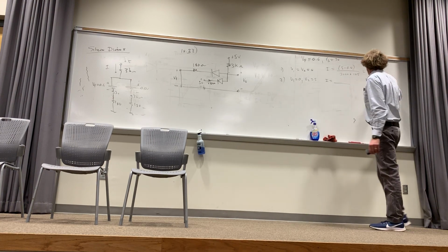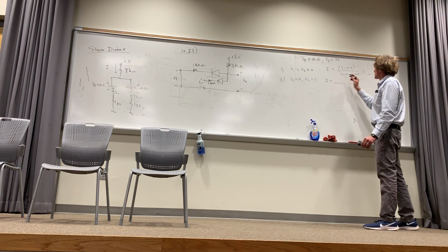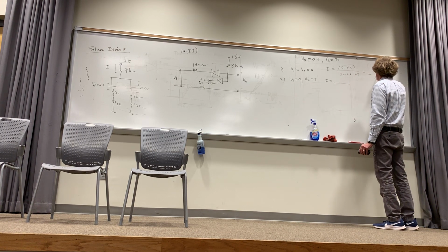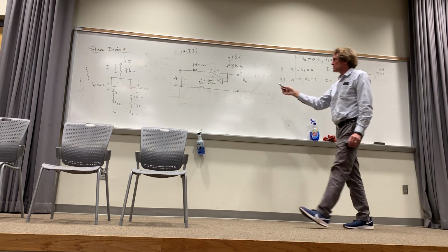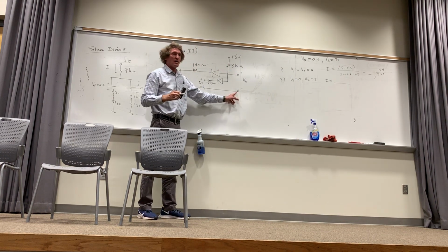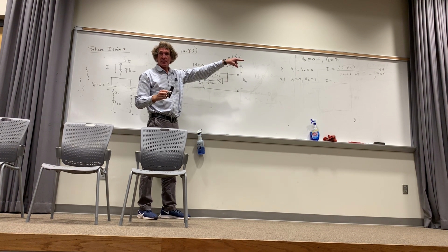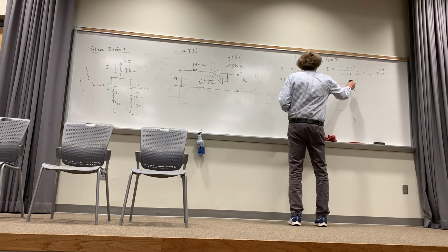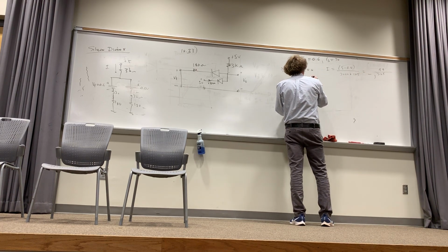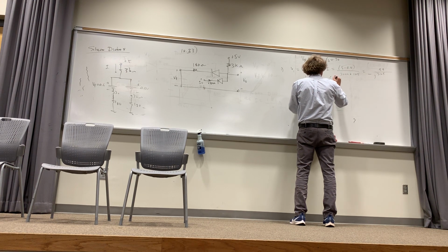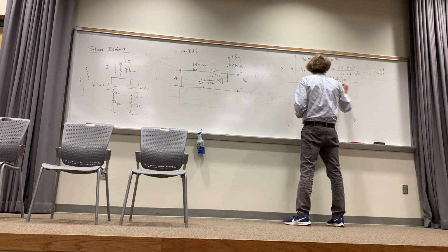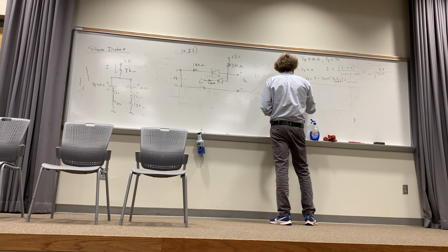What would V out be for this? That would be the current right there, but what would V out be if this is the current, right? Which is what? 4.4 divided by 3105 would be the current. Do you agree with me there? What would the voltage here be? Wouldn't it just be 5 minus 3K times that current? Y'all see that, class? So the actual voltage V out for this one would be 5 volts minus 3,000 times that I, which is 4.4 over 3105, and that would be the voltage V out for part 2, V1 equals 0, V2 equals 5.